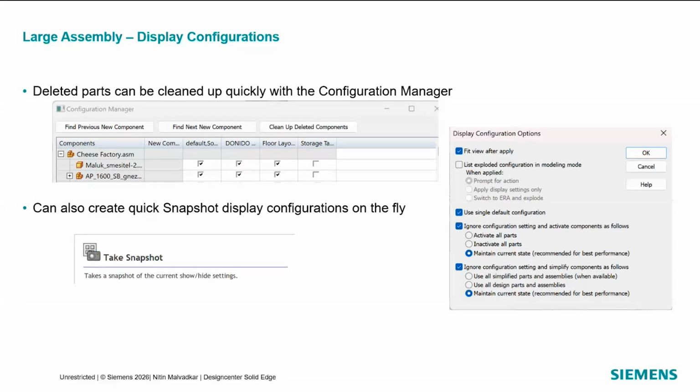Another useful tool is the configuration manager. The configuration manager can be used to clean up and quickly remove the components which are not required. So in case you have deleted some components from the assembly, these can be quickly removed and the display configurations can be accordingly updated.